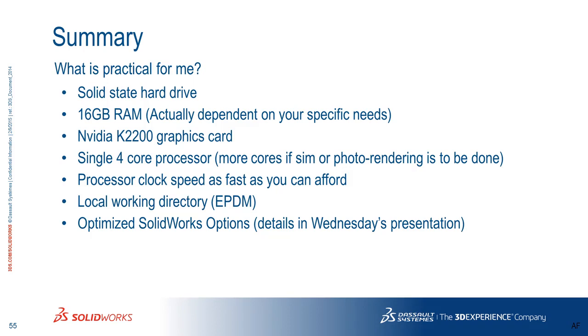Local working directory, please use a PDM system. For God's sakes, use a PDM system. If you're going across the network, PDM. Exactly. And then optimizing SOLIDWORKS options we'll deal with in Wednesday's presentation, along with a lot of other stuff that's a lot of fun. You'll like that presentation.